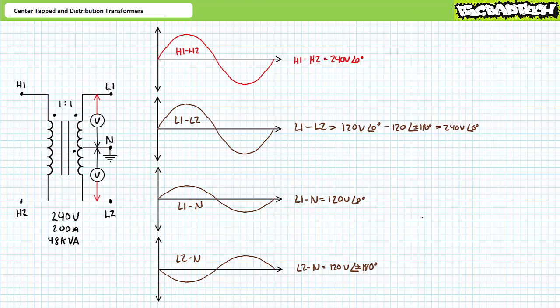240 volts comes into a distribution transformer and it's split into two 120 volt phases, L1 to neutral and L2 to neutral, equal in magnitude yet perfectly out of phase with one another. This type of system additionally allows 240 volts between L1 and L2 for larger electrical loads like water heaters, ovens, dryers, car chargers, and outlets for equipment like welders.